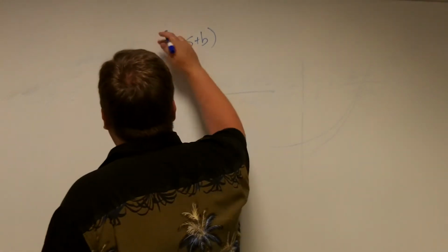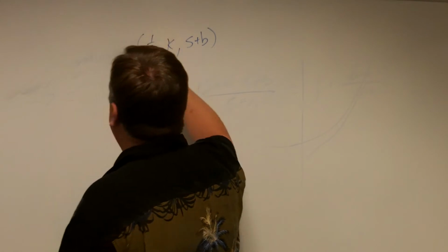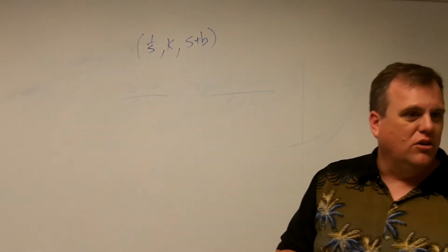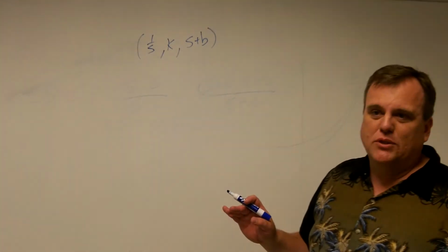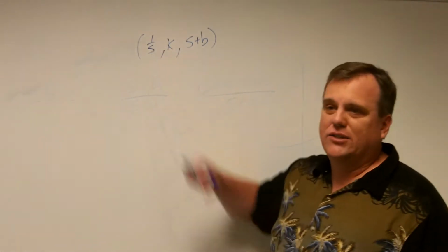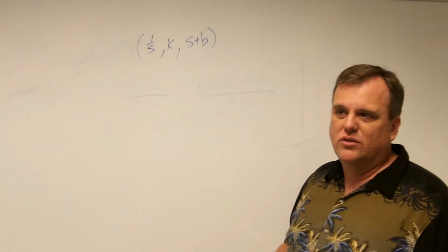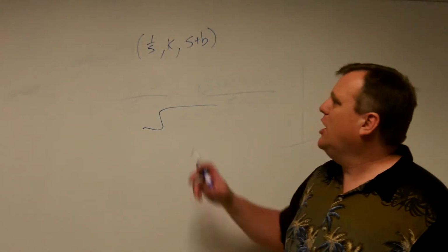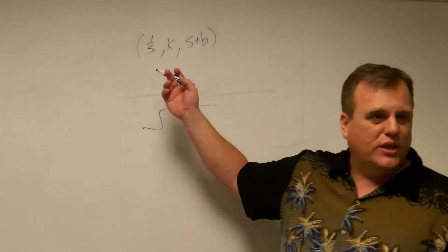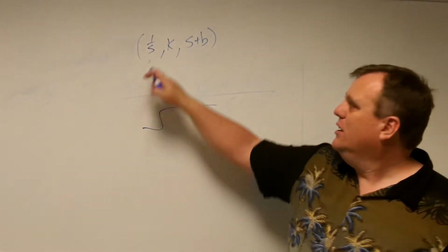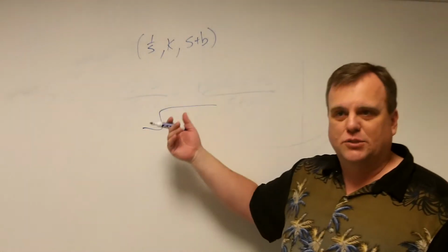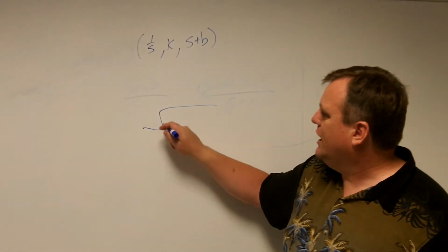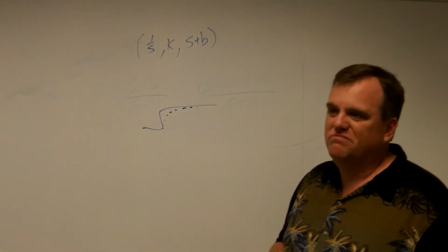Just as another side note, you will sometimes see people also do this one, kind of a 1 over s or a k over s type thing as it goes on. That's another fairly common one to stick in there. If you think about what really happens with that one, 1 over s ends up giving you what type of a function? A step. Right? So when you do synthetic division, which is how you separate that one up, you'll end up getting a step function and you'll get an exponential, and the exponential is usually negative. So the step function is here, and then you're taking an exponential subtracted off from it.